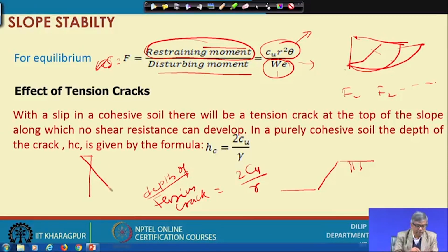Okay. The pressure diagram was something like this. This is 0 tension, and here is the maximum tension. This is a depth of 0, that means the tension crack can reach up to this, and this depth is called Hc. Since this is a negative pressure and this is a positive pressure, up to this much if I go, the total force, the area of this diagram, becomes equal. So up to that much depth, the wall is not getting any additional pressure. Because of that, we can excavate double the depth of the tension crack without support.